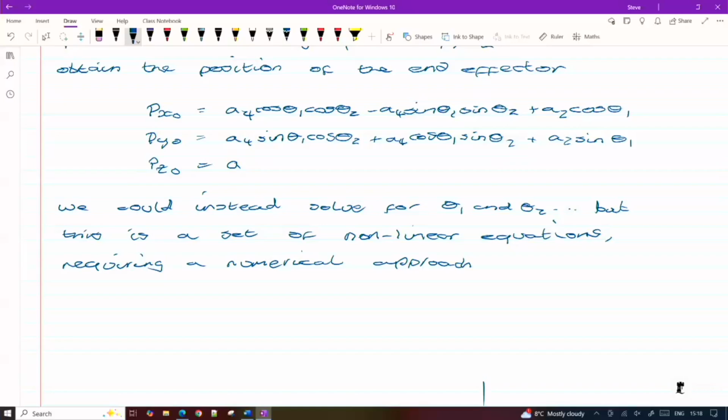So you take certain views of our robot manipulator that allow you to reduce the dimensionality of the problem by one. And from that, you can use simple trigonometric relationships, Pythagoras, the rule of cosines, etc., to come up with a set of equations that you can solve to give you the inverse kinematic solution. Okay, so that's where we got to last week,